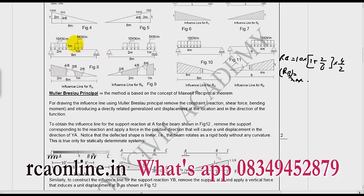So what do I have to find? I have to find the maximum value of RA. So what will be the position? This will be the position. RA will be maximum when this is the tail of the UDL and this is the head of the UDL. So the 5 kilonewton per meter load is ahead and the tail of the 10 kilonewton per meter load is at the A point. Then I will have the maximum area for RA.